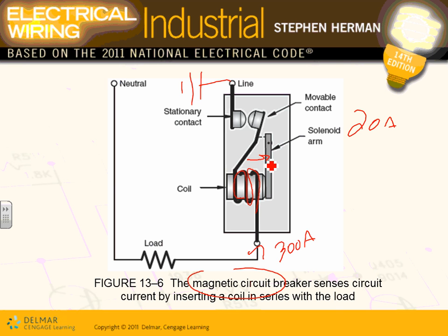So they open it based on, like a magnetic starter, guys, a coil. It energizes a coil, and the coil has a plunger or solenoid arm, and then pushes these contacts to open. So they use magnetism as a means of opening the circuit breaker instead of thermal. Magnetism. Does that make sense? Can you guys see how you energize the coil? It creates a magnetic force, pushes these contacts open. That's what happens inside that, if you have a short circuit. If you have an overload, there's a heating element that slowly, gently heats these bimetallic materials and trips. Any comments, gentlemen, any questions about the magnetic component of a circuit breaker?